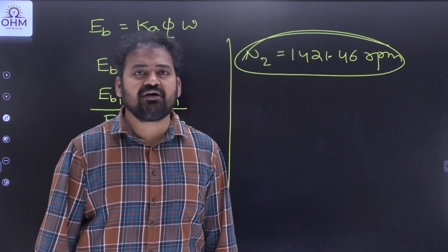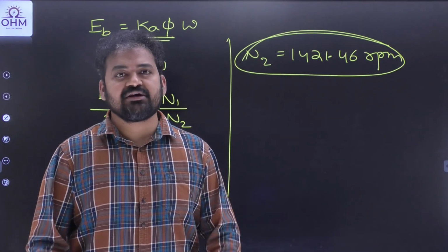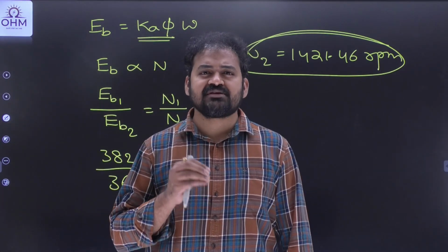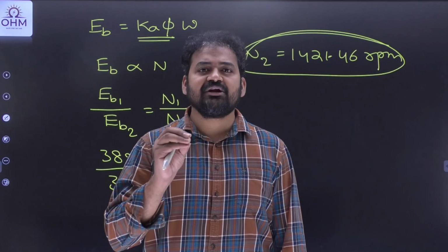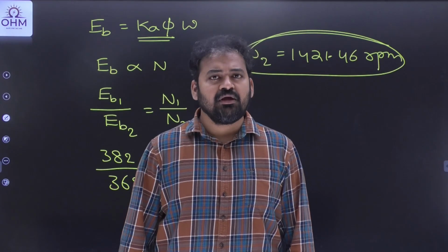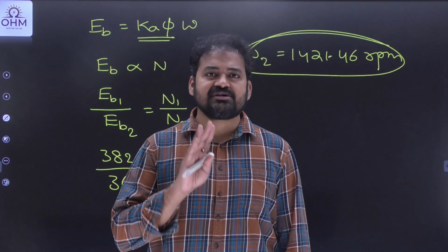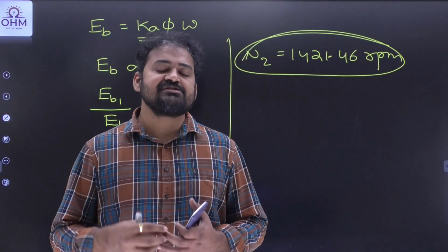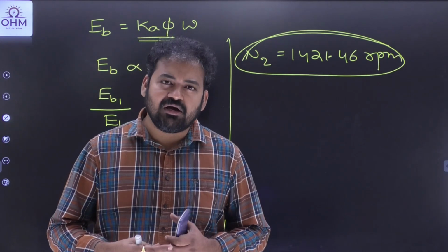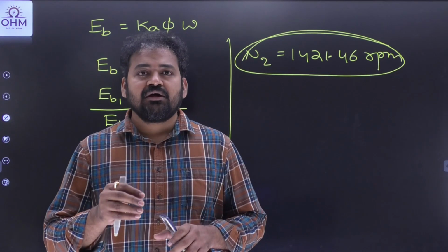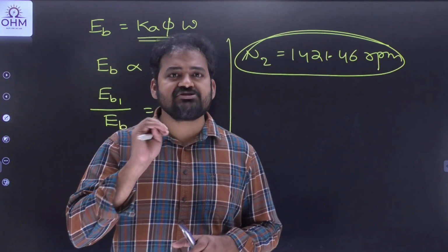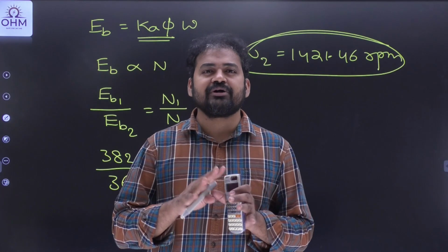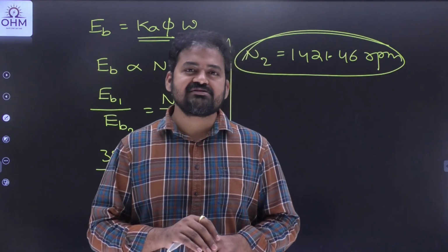These are the questions we have up to GATE 2023 examinations from DC machines, and you can understand after solving all these questions, majority of questions are coming from DC motors only, mainly from shunt motor, series motor, separately excited motors. Okay, so KVL equation, performance equation for back EMF. Most important thing is that you have to focus on whether flux is changing or not, whether armature current is changing or not. If you understand these 2 points, you can answer any question related to DC machine easily.